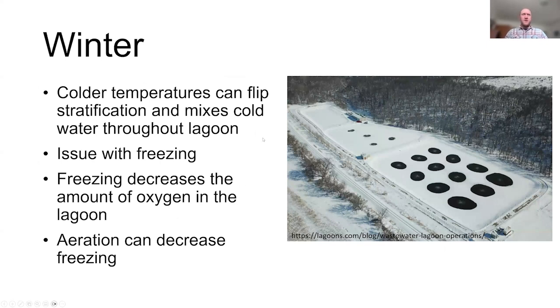And winter can also be harmful because it can really flip the profile of that lagoon. Colder temperature water is more dense than warmer water, so it can sink down and kind of mix up your whole lagoon, and that can be really unhelpful for your processes and just overall decreases the temperature throughout your lagoon. Kind of like what happens in lakes too, in colder climates. And then, of course, they can freeze.